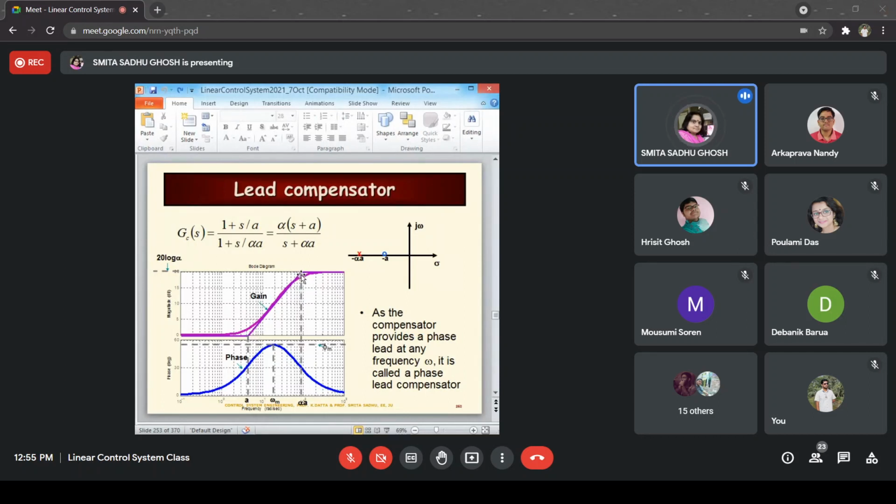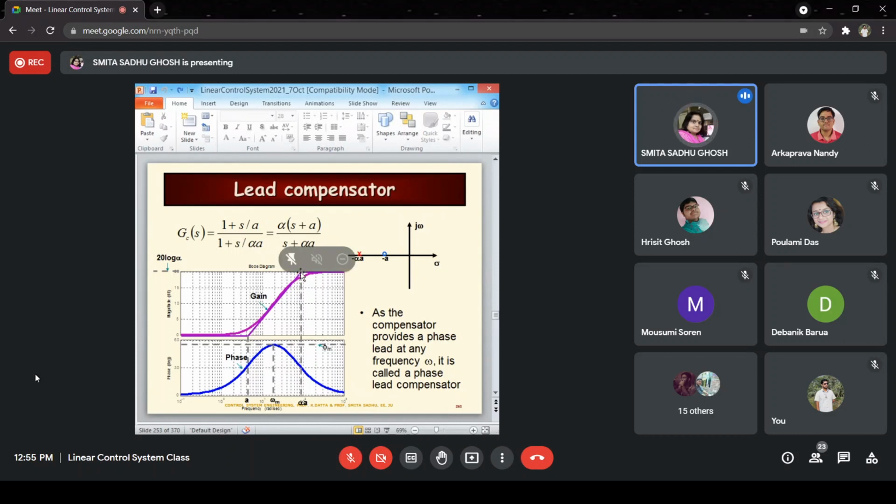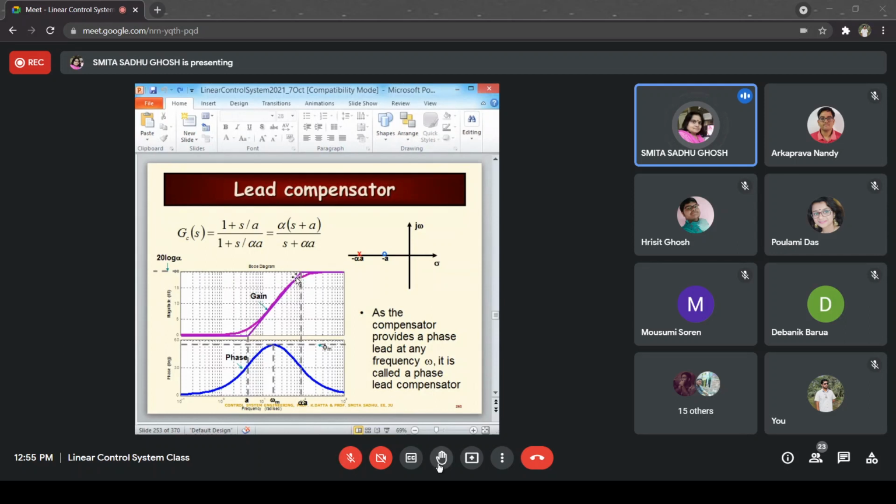So at the corner frequencies, the magnitude is going to be a bit different from the value of the magnitude of the asymptotic plot. By how much also is something which is known. It is going to be having a difference of 3 decibels. So when you have the 0 over here, the exact plot is going to be plus 3 dB added to this value of magnitude over here. On the other hand, where there is a pole, the plot is going to be down by 3 dB, meaning a minus 3 dB to be added to the plot which you have as asymptotic plot.